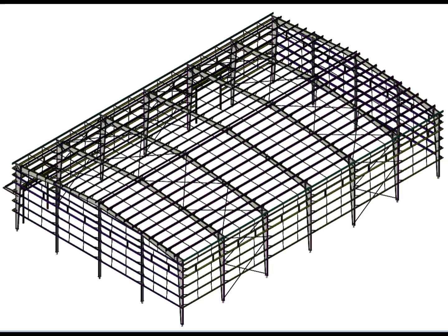When these views are combined, the PEB structure becomes much easier to understand. In this building, the girts work together with the columns, wall cladding, bracing and other secondary members to form the wall framing system. And this is why proper girt detailing is important for fabrication, erection, and coordination of the building.